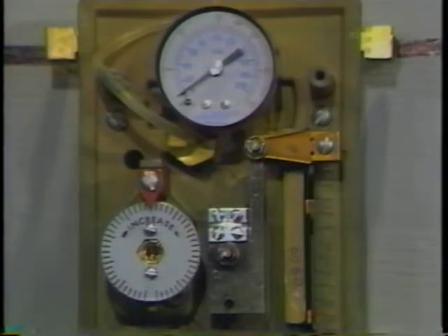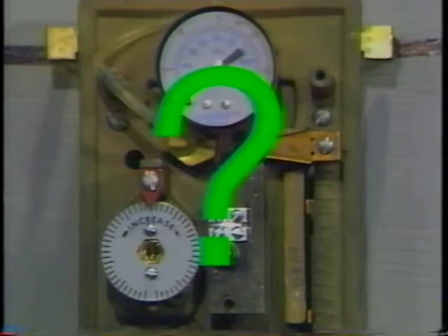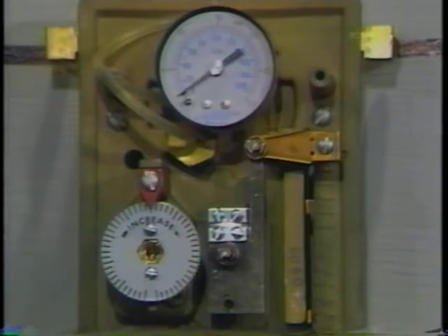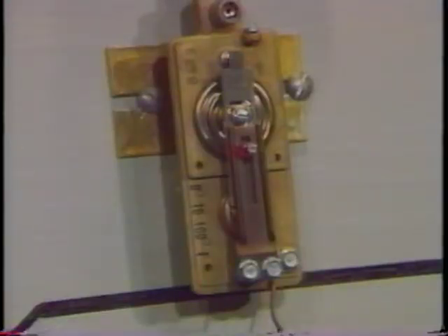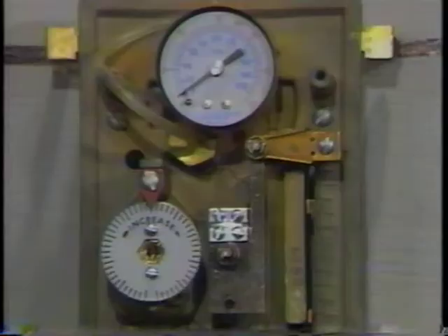The next step in calibration is to turn the set point dial to match the actual temperature. When I go to turn the set point dial, I find that there are no numbers, just 50 blank graduations. So how do I know where to position the dial? On any receiver controller, the set point dial gets its numbers from the particular transmitter range being used. Since we're using a 0 to 100 degree transmitter, this becomes a 0 to 100 degree set point dial.